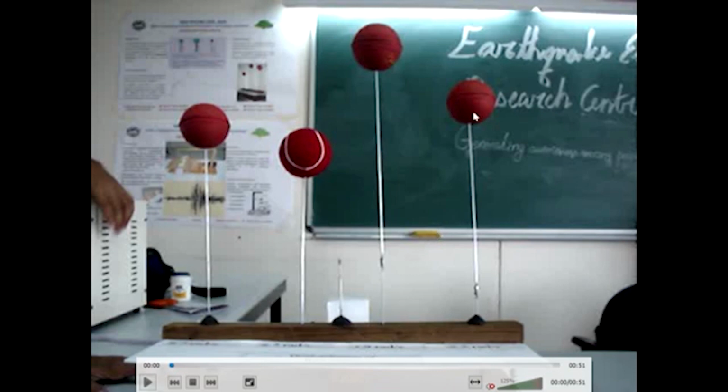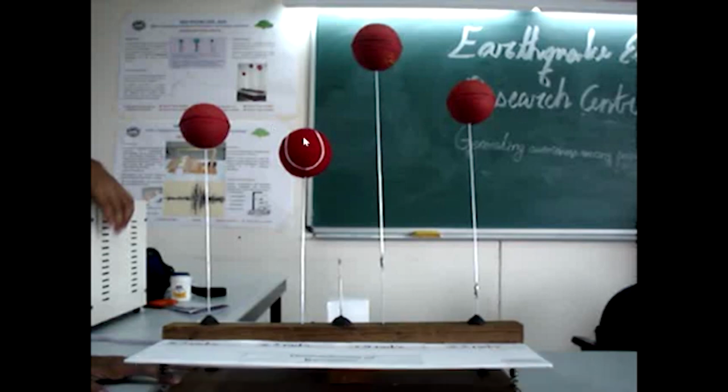The second one has a slightly lesser natural period, and the first structure, the left side structure, and the second structure are matched such that their periods are the same. That means the lengths of the buildings are slightly different, but the mass is adjusted such that both natural periods are the same. Now, if we excite all these buildings at some frequency, what is going to happen?